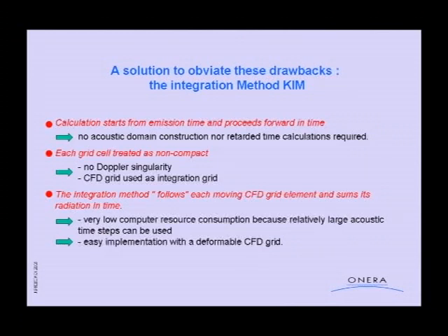Furthermore, the integration method follows the CFD grid elements and sums its radiation in time, so that relatively large acoustic time steps can be used. For the helicopter problems, the rotor rotates at a low frequency, so the input data vary essentially at low frequency, so that we need not very small time steps.